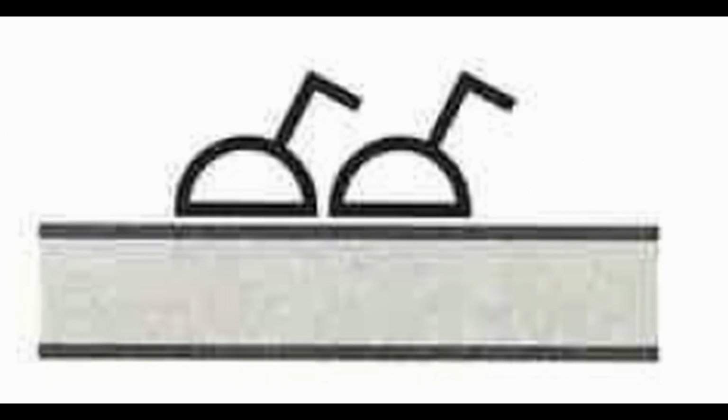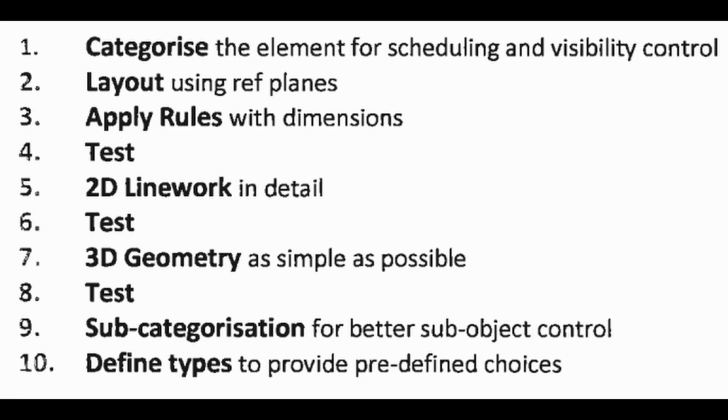2D symbolic lines improve clarity in plan and elevation views, reduce the processing load on your computer, allow you to follow industry drafting standards, and provide clean, readable drawings at any scale. 3D model lines, on the other hand, are used to simplify geometry without sacrificing accuracy. A grill, for example, doesn't need every slat modeled. A few model lines can represent it effectively. In this module, symbolic lines and model lines are introduced at the appropriate stage, reinforcing the idea that graphics and geometry serve different purposes.